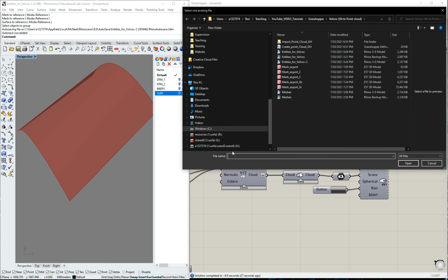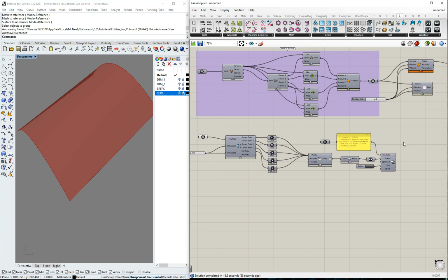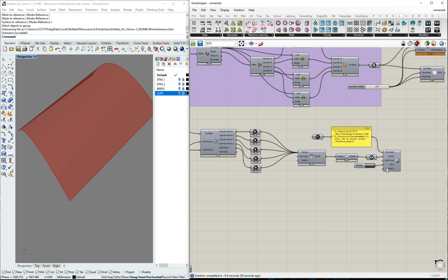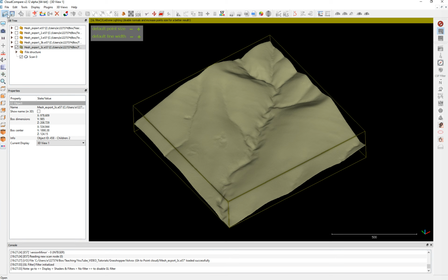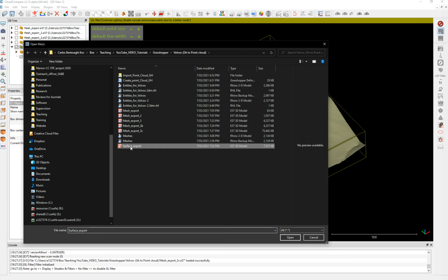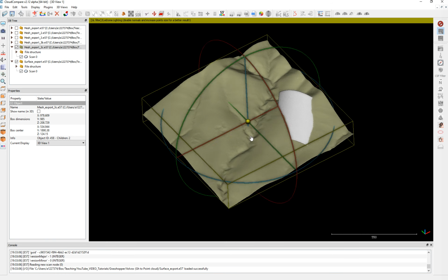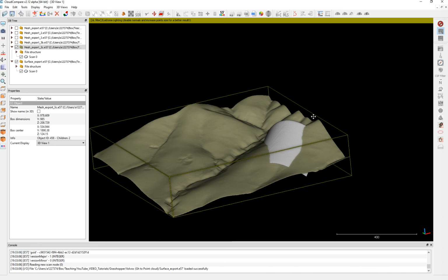We're gonna change the name. We're gonna put now it should be surface, right? Surface export. Okay. Now it's a surface we're exporting, and we click saving. That's the good thing of this. And the surface has been exported. And we come here, look at this surface export, and it will export it on top of it, using the same origin. The color, of course, is completely different.